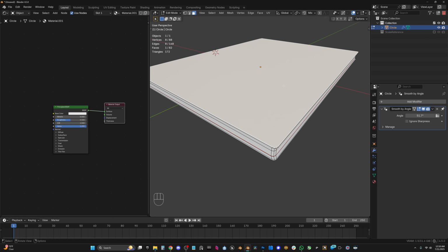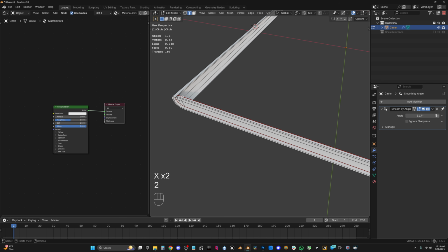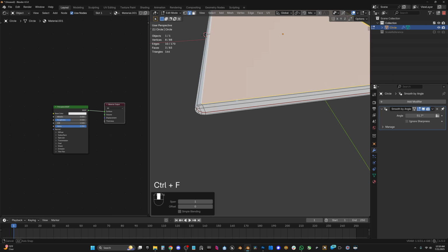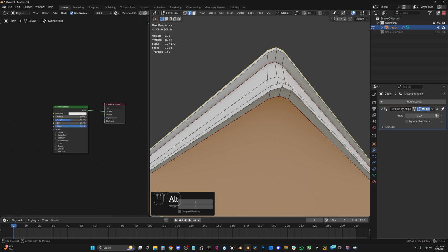There's a few ways you could do this. One way, let's just delete that face on the top and the bottom. Then let's select that edge loop here and let's try to do a grid fill. Beautiful, that worked great. And now we have quads. Let's do the same thing down here, Control F grid fill.